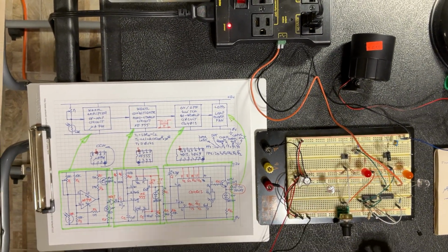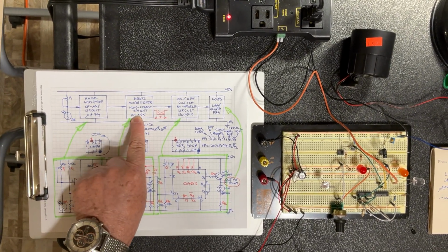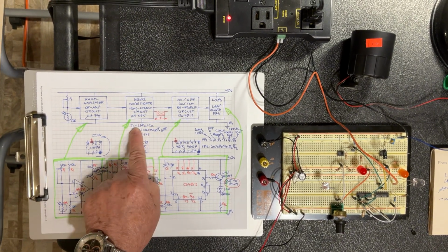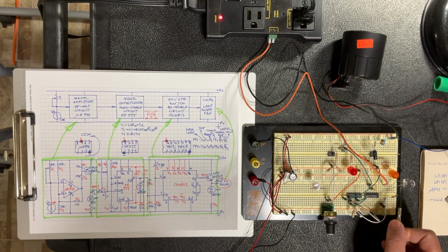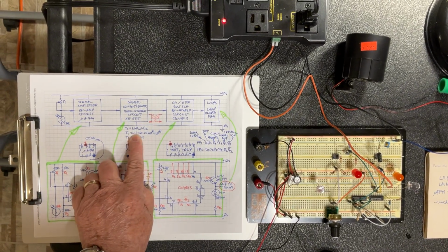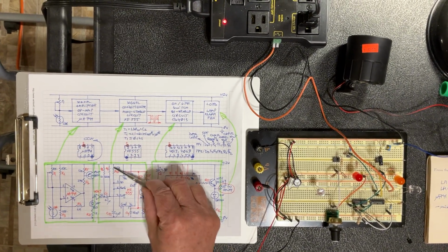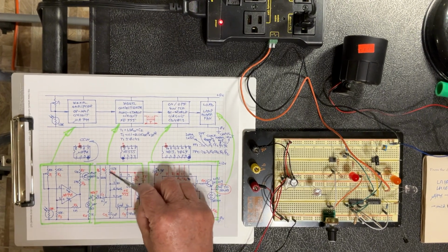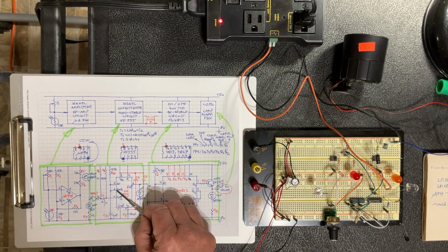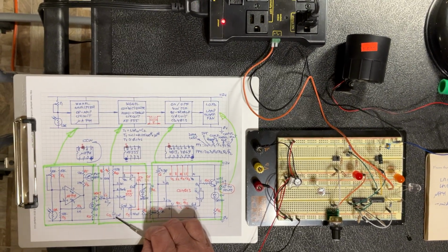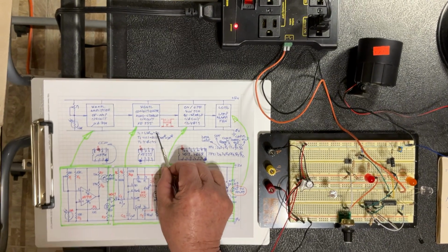How does it happen? It happens because when you build the monostable with the 555, there is a little formula to use in order to calculate the duration for how long the light stays on. I'm talking about the amber light. It's 1.1 times the resistor times the capacitor. What resistor, what capacitor? Exactly that resistor here, R10 in our diagram, which is related to both pins 7 and 6. And the capacitor is C2, this one here, which is 1 microfarad. The formula is 1.1 times the resistor times the capacitor.